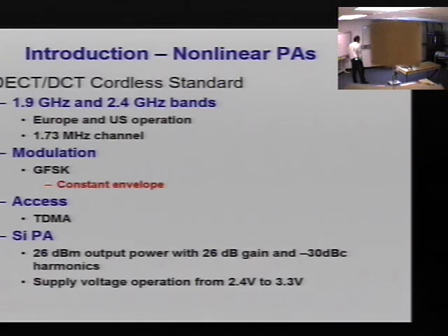The overall top level idea is 26 dBm output power, and you really want to relieve pressure on the preamp, primarily because that's integrated into the transceiver. The preamp is coming off differential, and it's very difficult even to get 0 dBm out of that transceiver chip. There are a lot of issues involved, and that's a CMOS chip. So it puts a lot of pressure on the PA end to meet power gain numbers and of course power.